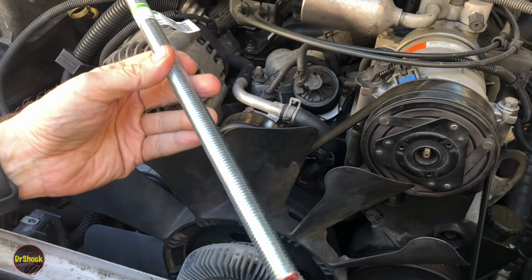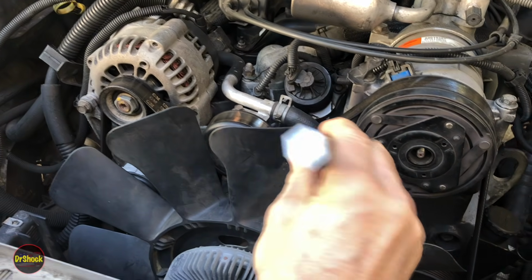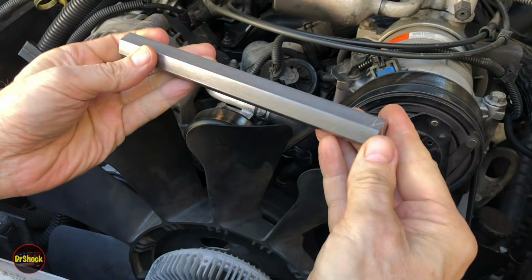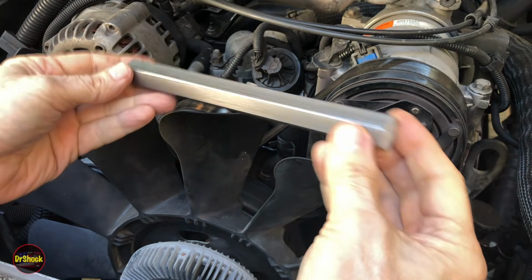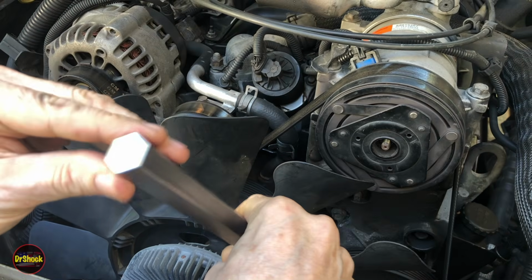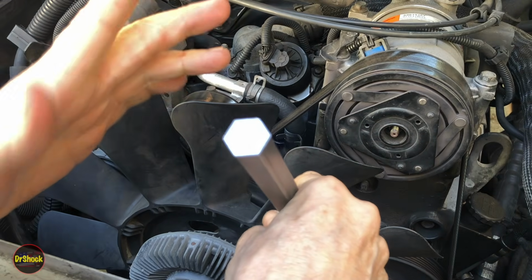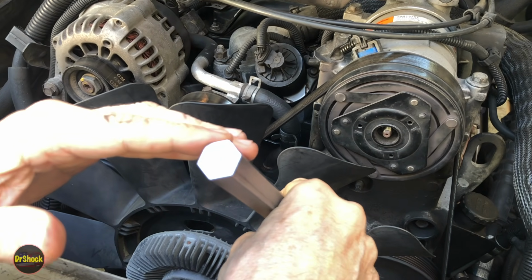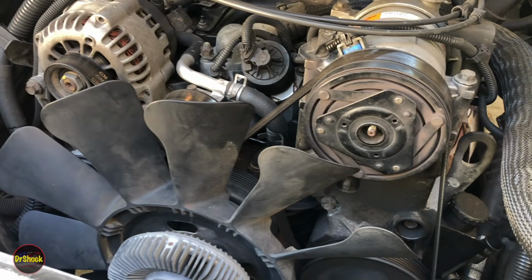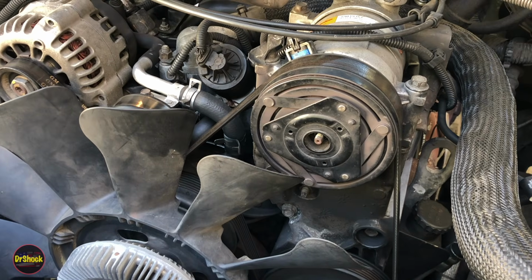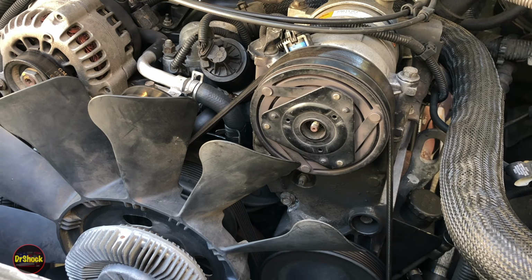The other option would be take some 3/4 inch hex steel rod. This is 12L14 alloy, so it'd be good to machine, and replicate the tool, and this time instead of M9 by 1.25, tap it for M8 by 1.25. And of the two options, that's what I decided to do. So I took this rod down to a local machine shop that I work with and asked them to fabricate this for me.